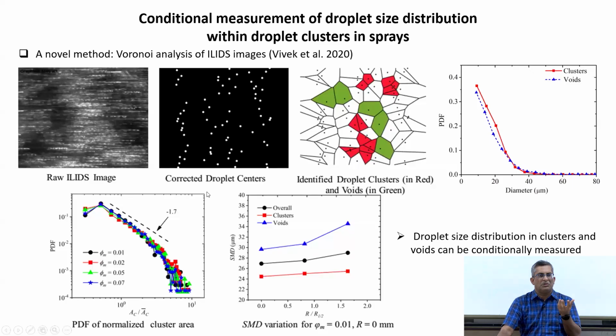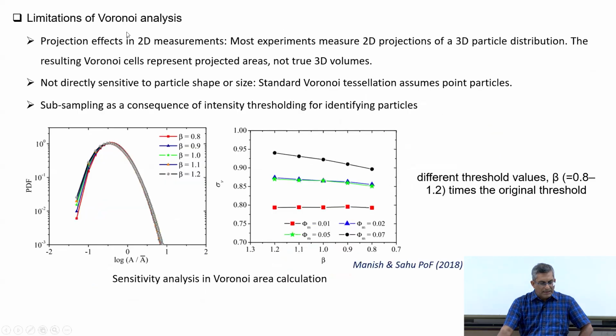Okay. So, this is a novel application, but considering that the applicability of the ILIDS technique is only for dilute sprays, you can use this technique, or Voronoi analysis of ILIDS images, only for dilute loading. So, finally, there are some limitations of Voronoi analysis also.